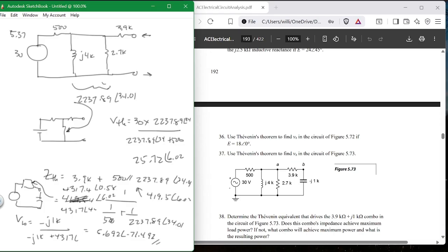Determine the circulating current by saying 10 divided by 10K, or 1 milliamp peak to peak is I. Then you measure your V divided by your I, and that gives you your X. There is no J in that X. You could drop the J. I know there's supposed to be a J in there, but you can ignore it. Sometimes you can, sometimes you can't. Here you can't ignore it.